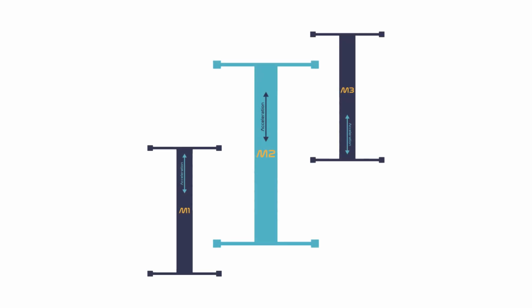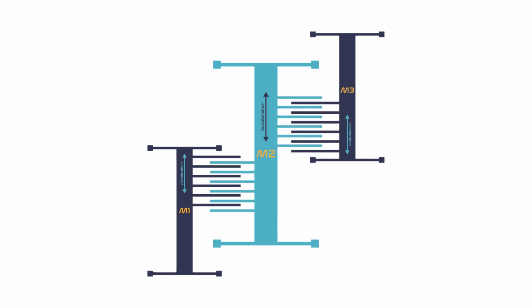To address this challenge, we developed a MEMS network composed of 3 interconnected units, M1 at the bottom, M3 on top, and M2 in the center. Each unit can be designed with different parameters for various applications. M2, being the largest unit, has the highest sensitivity to acceleration, allowing it to move first. The MEMS units are electrically coupled through parallel plates extending from each mass, with coupling plates labeled P3-2 between M2 and M3, and P1-2 between M2 and M1.